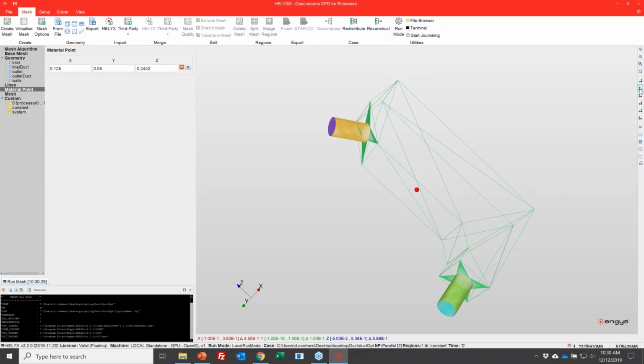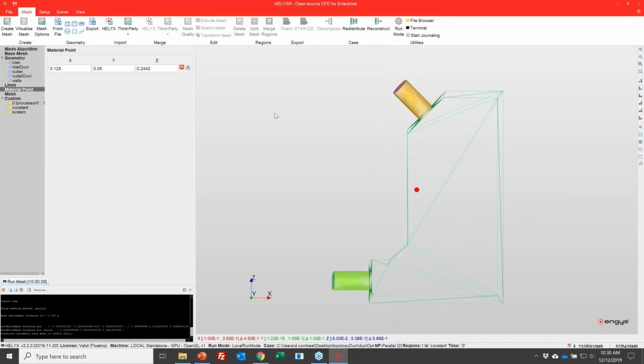And the mesher itself, like I mentioned before, is a cut cell approach, and there are several other commercial codes that offer a similar approach. The reason we like this is because this type of mesher is quality driven. When I say quality driven, I mean we prescribe a set of metrics: skewness, aspect ratio, the amount of twist that a cell might have.